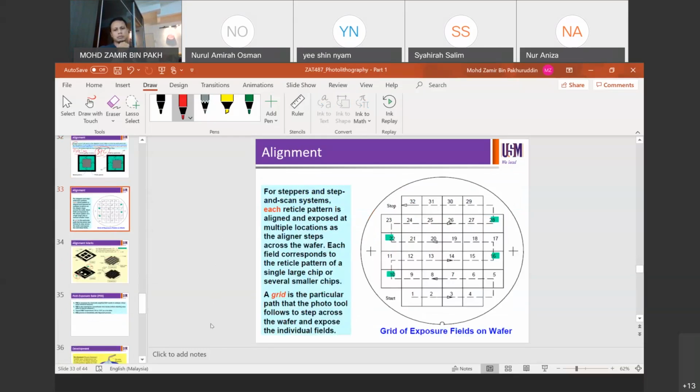Okay, so alignment is what you have to do during the exposure system. So this is the notch as what we've discussed before. So before you actually do the scanning process or the exposure process, the wafer has to be aligned at the home position. Then only the scanning process will take place. Okay, so just imagine if the notch alignment is not happening, your notch might end up here, for example, and you will have your theta overlay off so much in comparison to the previous layers. Kalau you print satu single layer je, it's okay because it doesn't depend on anything, and you can print in any theta you like. Your notch can be anywhere, but the moment you print on tens of other previous layers, they have to stack. Kalau tidak, dia akan jadi cacar merbah. Okay.